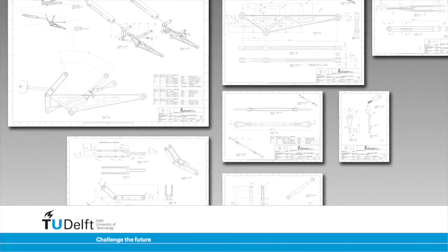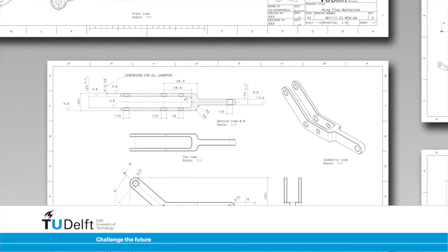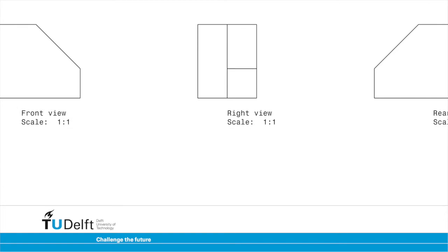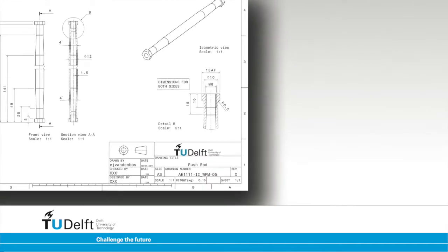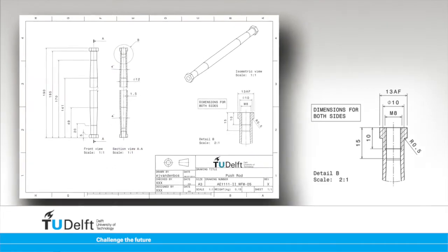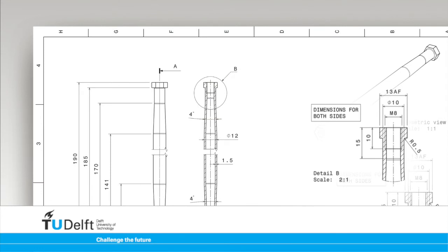Sometimes other projection views can be seen in engineering drawings. As well as section views and the orthogonal projection views such as front, left, right, top, bottom and rear view, detail views can be presented. If the detail is present in a certain projection view, this is the origin view for the detail view. In the origin view, a circle or another geometric item is drawn with the thin continuous line type to indicate the detail's position.